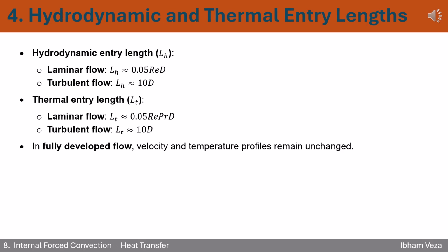4. Hydrodynamic and thermal entry lengths. Let's simplify how entry lengths work in internal flow. When fluid enters a pipe, it doesn't instantly develop smooth profiles. It takes some distance before the velocity and temperature settle into a stable pattern. This is what we call the entry length.